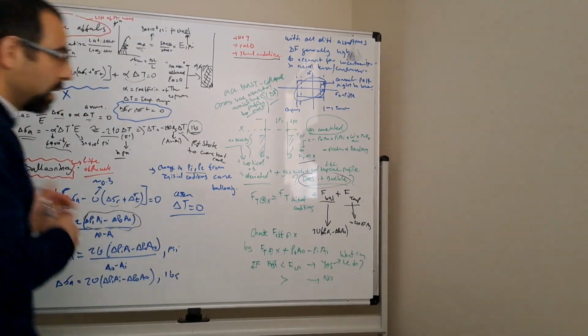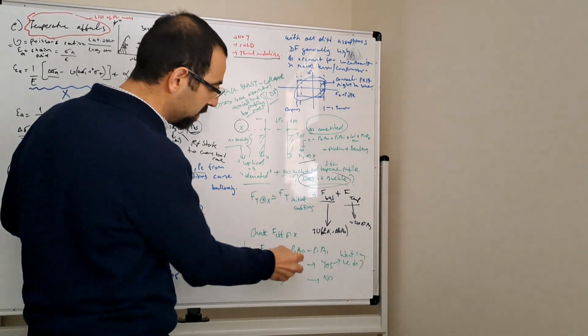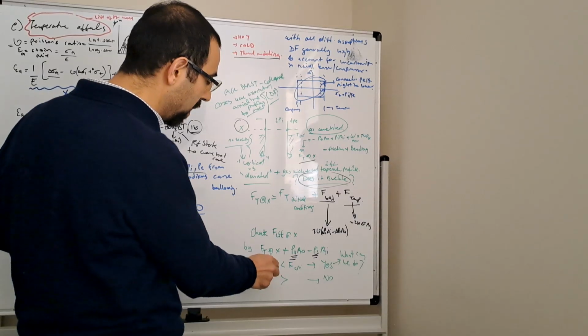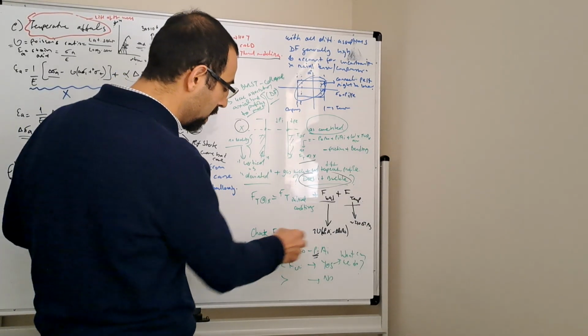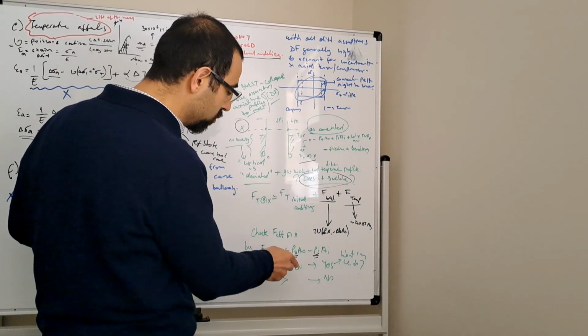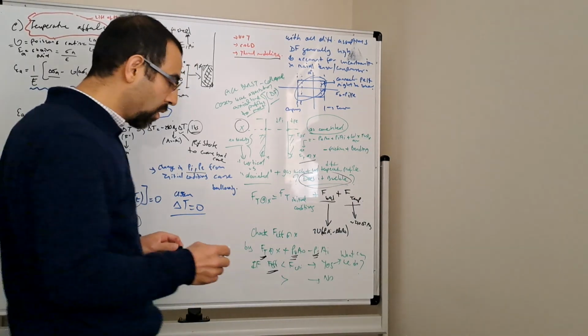So here I go to X and look at the gas kick, what my outer pressure is and what my inner pressure is, and then I take the balance and sum it with the true tension to get back the effective tension, which is a fictitious force, as we call it.